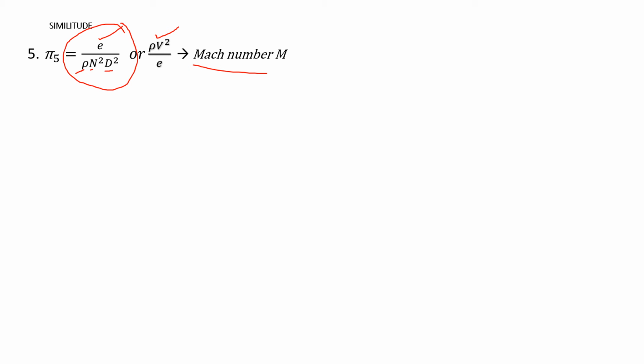The importance of the Mach number comes when we consider compressible fluids. When you start studying compressible fluids, the Mach number and its importance come in. Basically, the Mach number is the ratio of the velocity of the fluid to the velocity of sound.